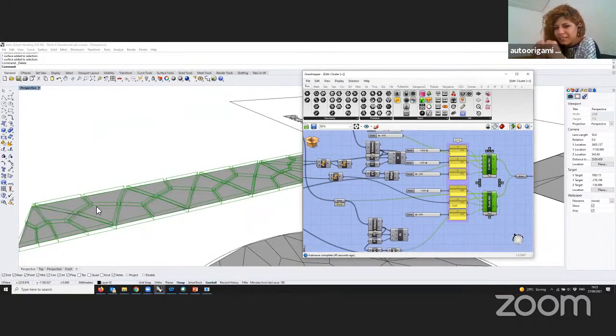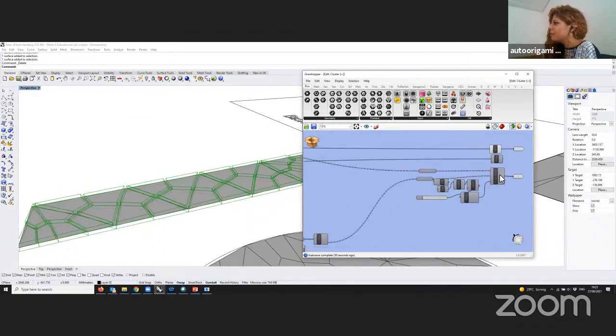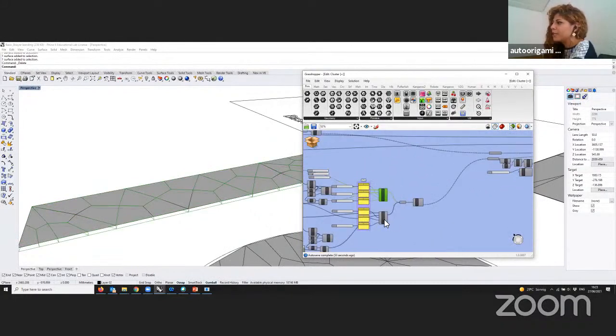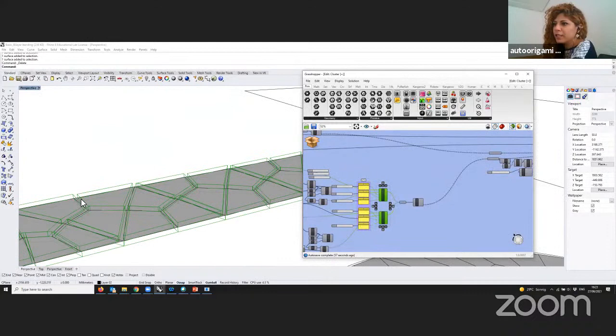but this top layer, all the faces are shrinking. And then the shape matching goal that we've defined in Kangaroo is basically saying to try to bring all of these mesh faces together again, connected the same way it was connected before. So this way we are saying that this upper layer, we are shrinking it, and the solver basically solves how these faces can go back together, and to do that, the overall structure needs to bend.